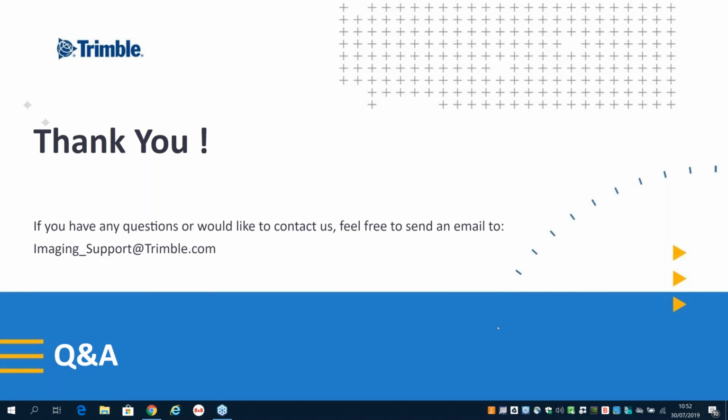Another one, it says, is it better to have a physical CORS base station with a large radius, for example, 10 kilometers, or a virtual base station with a shorter distance? Well, I think it doesn't make much difference here if you have CORS or a virtual base station, but I would say the closer the better, of course, because of the ppm. So I would go for the virtual base station at 2 kilometers because why not? Maybe this would save me 1 millimeter or 2 millimeters. It's not so bad, but also having a CORS base station at 10 kilometers is still great. So I think you would not even notice the difference.